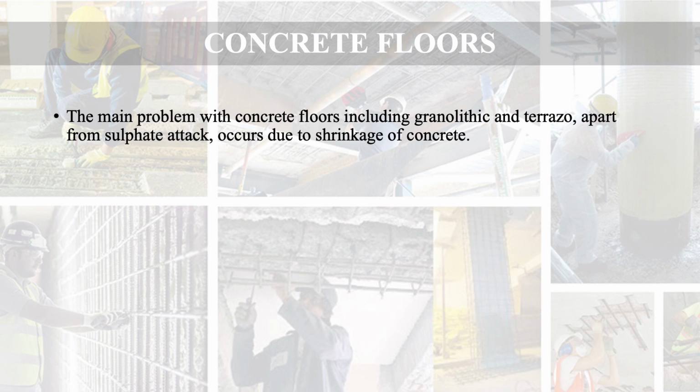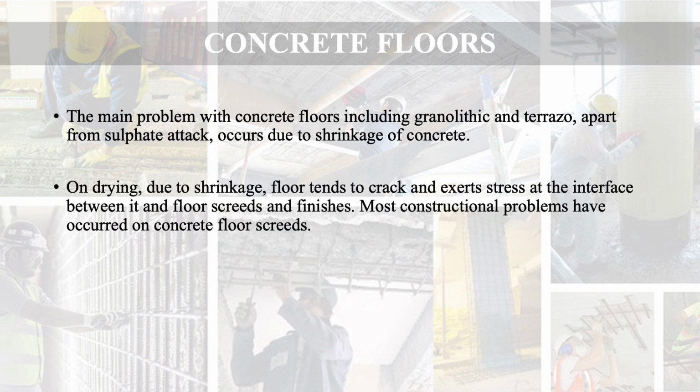The main problem with concrete floors, including granolithic and terrazzo, apart from sulfate attack, is the shrinkage of concrete. Here the shrinkage of concrete is a very big problem. On drying, due to shrinkage, the floor tends to crack and exert stress at the interface between the floor and the floor screed and finishes. Most constructional problems have occurred on concrete floor screeds. Means that screeds are the most affected portion.